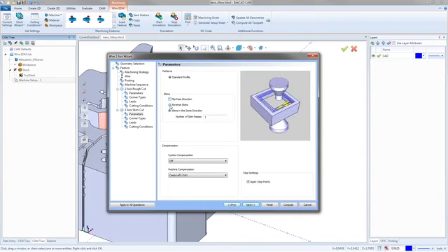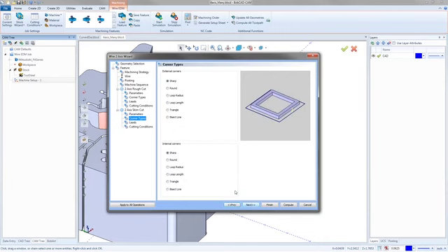You can also say with your skim passes, you want to reverse them as they cut. So skims in the same direction keeps everything moving the same direction. Reverse skims is going to cut one, let's say clockwise. The second one after that would be counterclockwise, and then another clockwise, however many skim passes we set up. So I'll just say keep skims in the same direction. System compensation's off, machine compensation on, and then I'll hit Next.